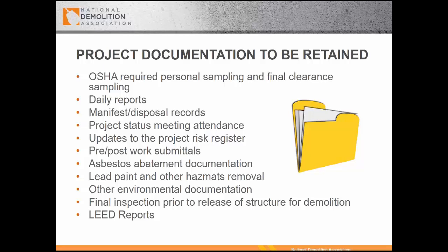Pre and post work submittals. Obviously, you need to keep those. Anything that you've developed that you could use on the next project, it is wise to keep so that you have that information. Other environmental documentation obviously needs to be filed. Most of the asbestos training and other information pertaining to asbestos needs to be maintained for 30 years.